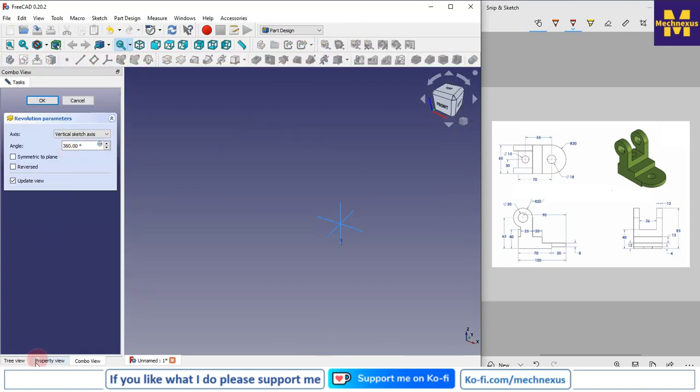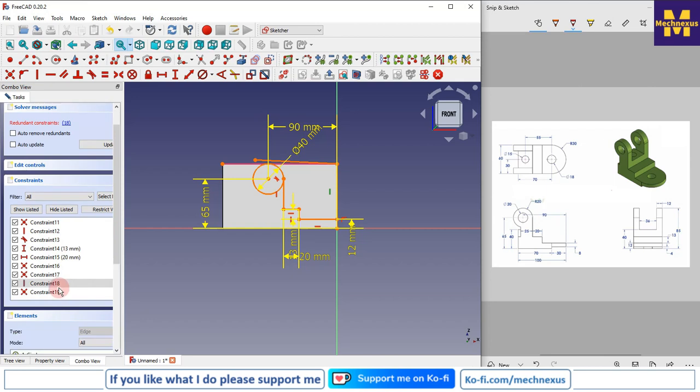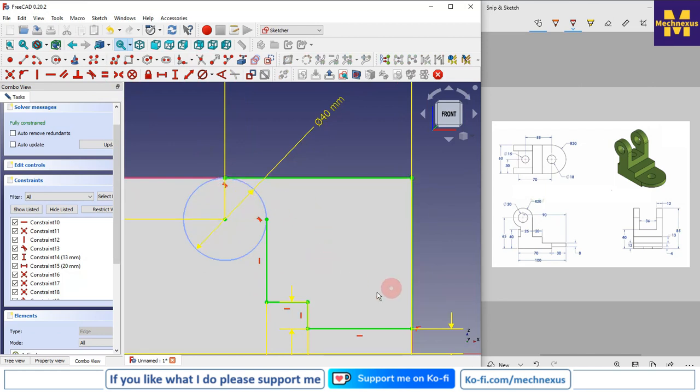Now I will edit my sketch. I will delete this constraint 18. Now I will make this and this tangent, and I will remove this extra geometry, and now we will use the 3-point arc to close our profile.